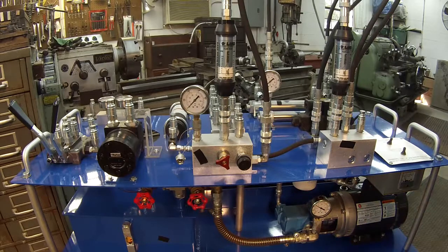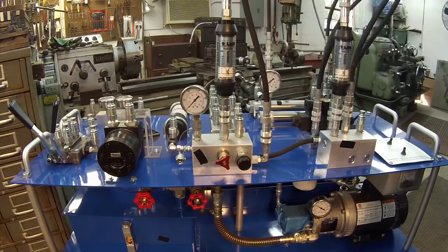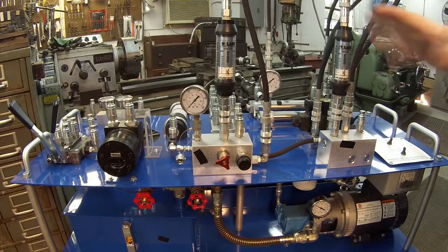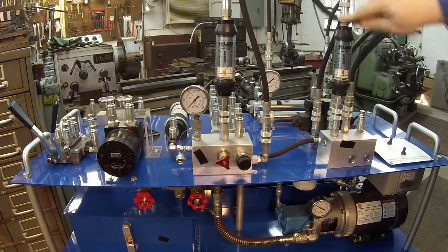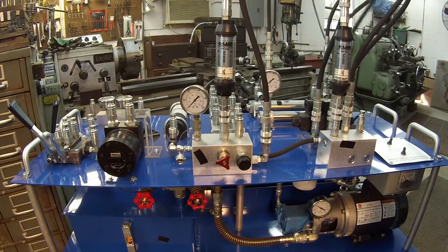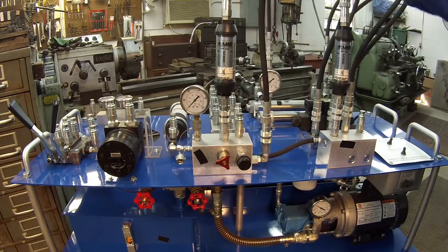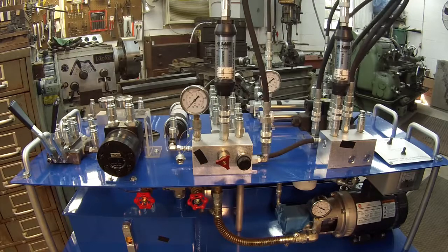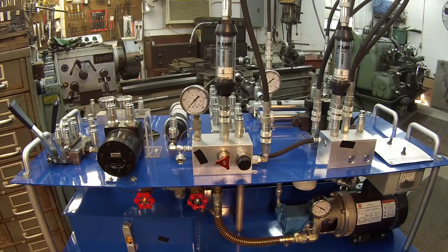Another one is not being supported properly. You have to have pipe and hose clamps and supports in your hydraulic system, or these things will start rubbing together like this. You don't want these things rubbing together because they'll start fracturing, and that's the number one cause of safety problems in hydraulics: slips, trips, and falls, and oil injection. So if you have a hose that's rubbing on another one and it starts spraying right here and you walk up there and touch it with your finger, you'll get injected with oil, and we'll talk about that in the safety part.